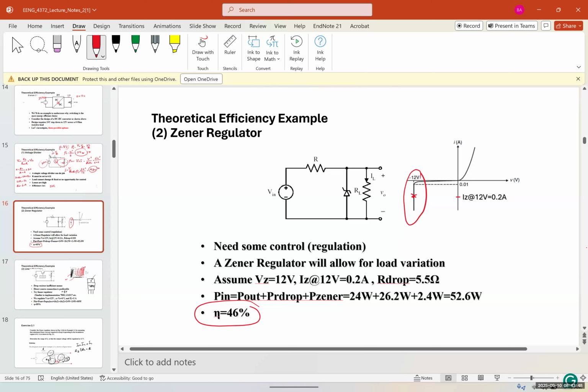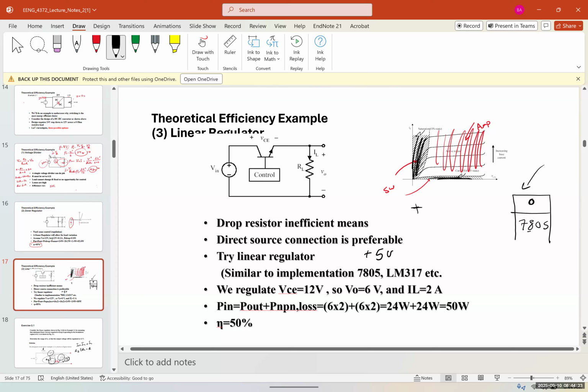So it was an IC that looked like this. You had a heat sink, and for example, 7805. If it starts with 78, it's a positive voltage regulator, and 7805 is a positive 5 volt, for example. A voltage regulator is technically a transistor with a controller.